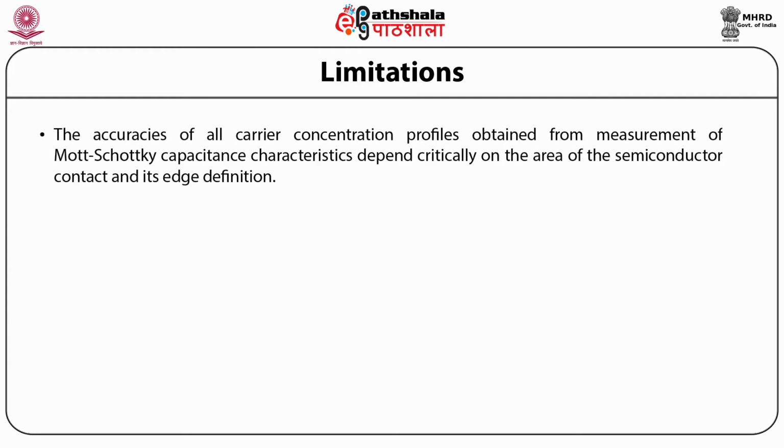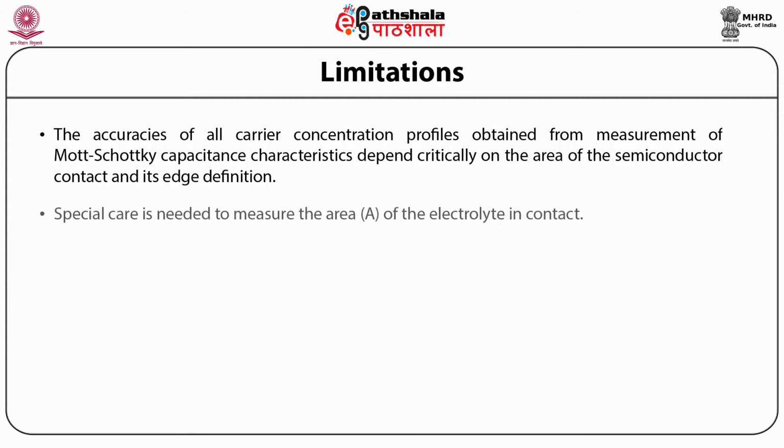The accuracy of all carrier concentration profiles obtained from the measurement of Schottky capacitance characteristics depends critically on the area of the semiconductor contact and its edge definition. Special care is needed to measure the area of the electrolyte in contact.